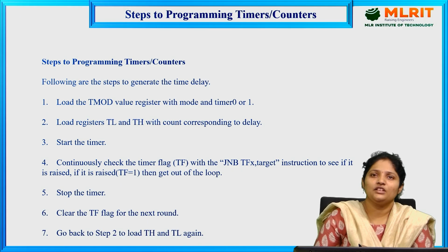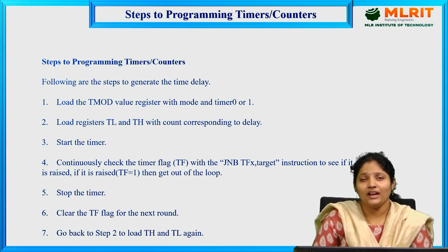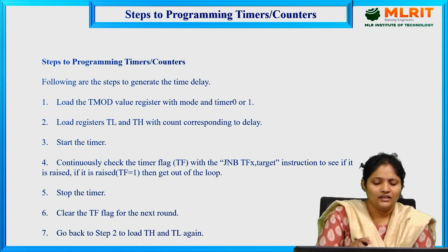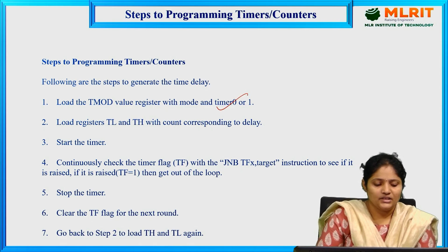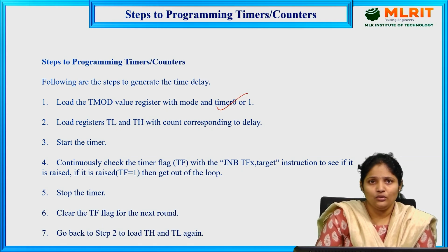To select which timer, whether we are selecting timer 1 or timer 0, and in these timers which mode we are using, it always depends upon the value that we are setting in the timer mode register. Next step, we need to load the delay values in TL and TH